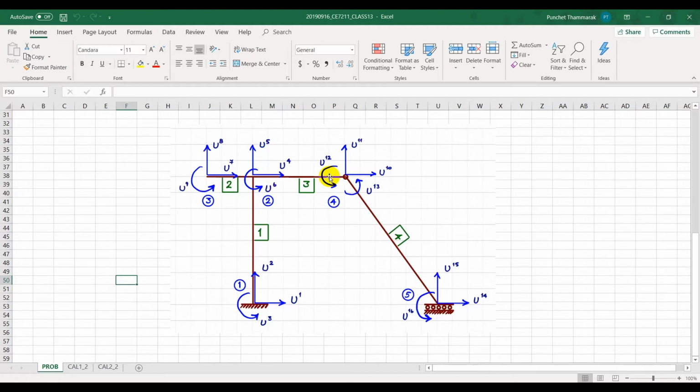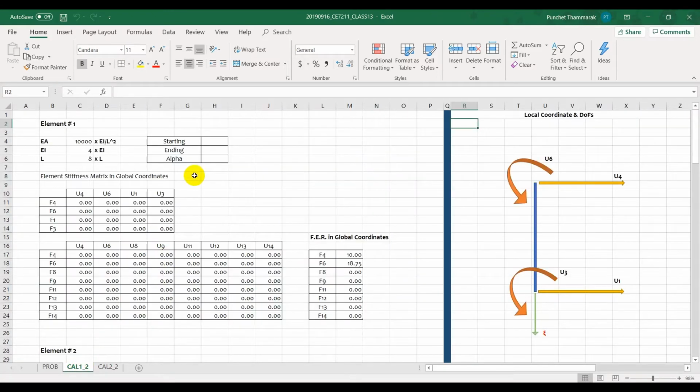That means the transverse degree of freedom in local coordinates for the beam is actually aligned with either x or y. That means we can set up the stiffness matrix without the use of coordinate transformation. Anyway, we have to set up the starting node and the ending node in a way that helps facilitate that operation.